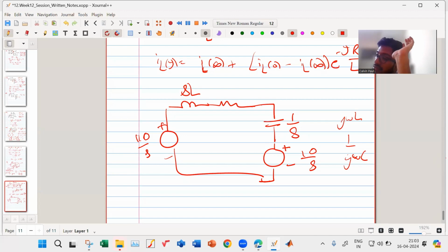So when they are not specifying that, we cannot apply the Laplace transform directly. In those cases they only want the RMS voltage across the capacitor, or the RMS current. They don't want the phase information, so it is not required. If you have the RMS value of your voltage, you can get the RMS value of your other quantities as well. Phase is not required.